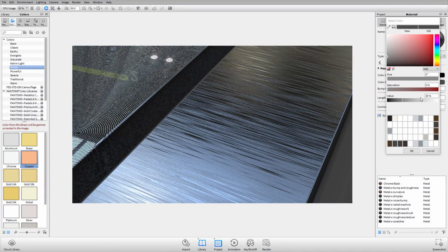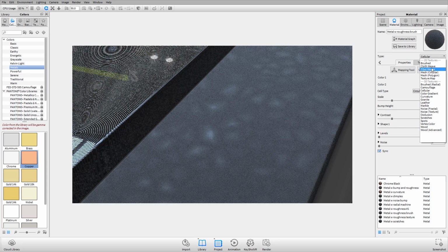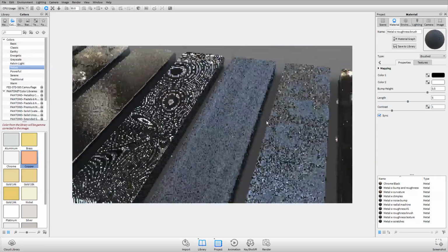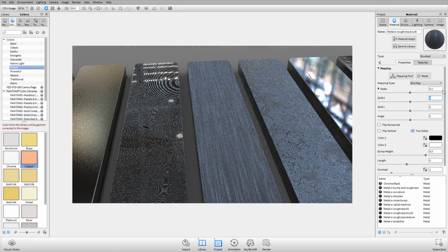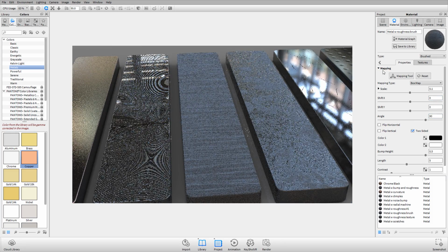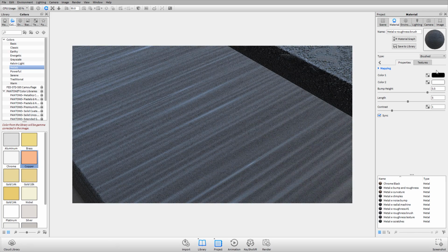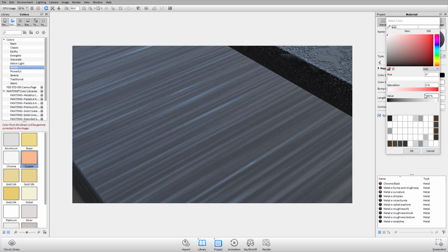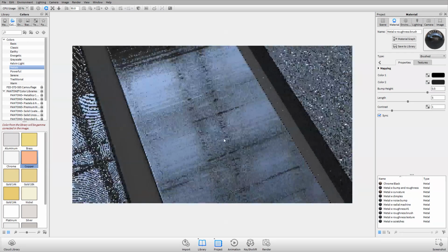So the default, whenever you throw this on, let's say we change that to brushed, and let's see what the default looks like. Okay, so it's too big. We can scale that down, and then I think in this one we rotate it at 90 degrees, and you'll notice that the brush texture has two colors. So roughness of black means smooth, white means completely rough, totally matte. So we'll change that and we'll drop it down to a darker gray. And now we're getting an interesting texture.